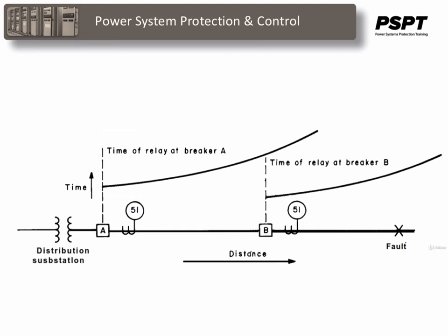In other words, we have a total inrush current, also referred to as cold load pickup, that may be approximately 4 times the normal peak load current. This inrush current decays very slowly and will be approximately 1.5 times the normal peak current after as much as 3 or 4 seconds. So in these cases, it might be wise to choose a more inverse or extremely inverse characteristic type relay that provides selectivity between the inrush and the short circuit currents.